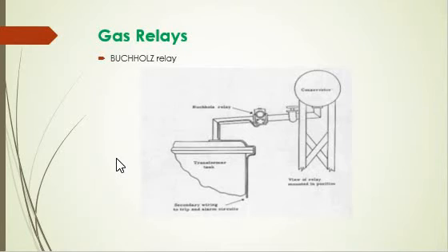A single relay is used to detect these two conditions. The relay is mounted at the top of the transformer with a pipe from the relay to the conservator tank. Any gas formed in the transformer will collect in the top section of the relay, depressing the float. This registers on a gauge on the front of the relay and will indicate a gas accumulation alarm. This accumulated gas can be drawn from the relay for analysis.